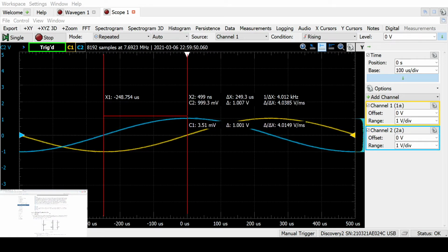Alright, so in the following ones, you will introduce individual components and then determine phase, lead and lag in different situations. So in the first one you have resistors. We will simply connect two resistors in series. Channel 1 will be connected across R1, channel 2 across R2.